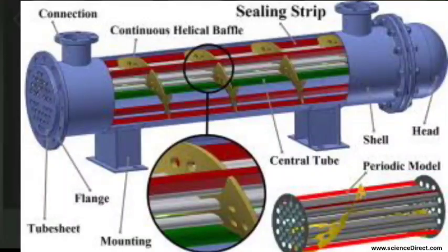But as per thermal requirement, we have to provide sealing so as not to violate the C stream, D stream, E stream. If the baffle cut is vertical, we have to provide a vertical sealing strip. If the baffle cut is horizontal, we have to provide a horizontal sealing strip. This is our first thumb rule.